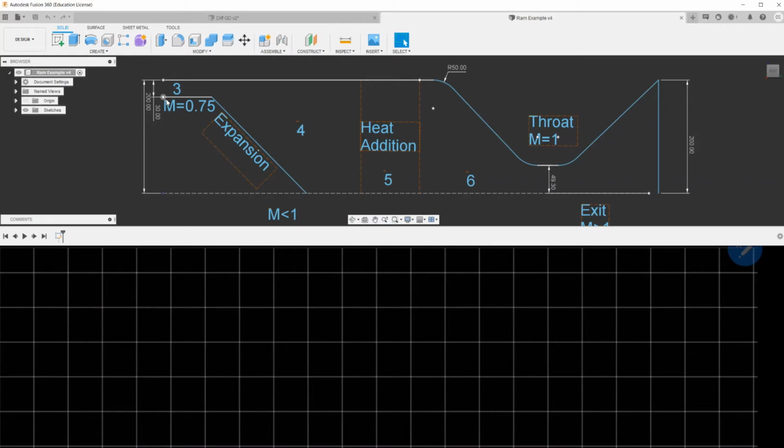This happens in several cases, right? When you constrain too much, or when you add so much heat that this structure cannot sustain it. For example, you add heat that would accelerate the flow to Mach 1 and further, to bigger values. Physically it's not possible to accelerate more than Mach 1 in a constant area duct, and the model predicts that it's not possible.